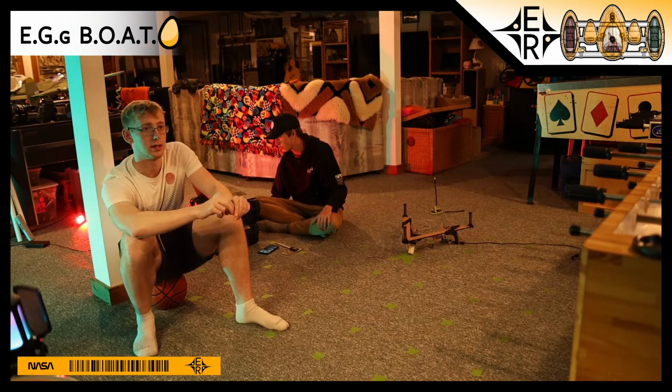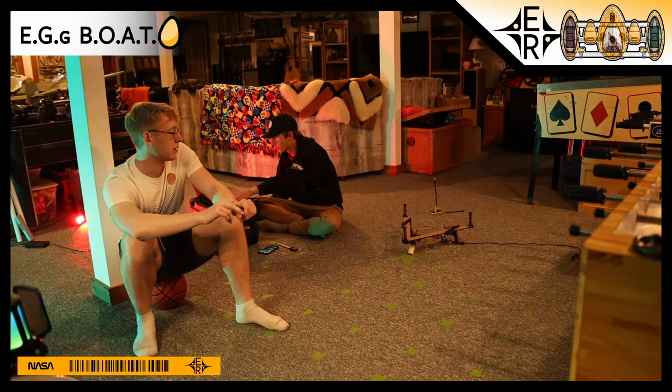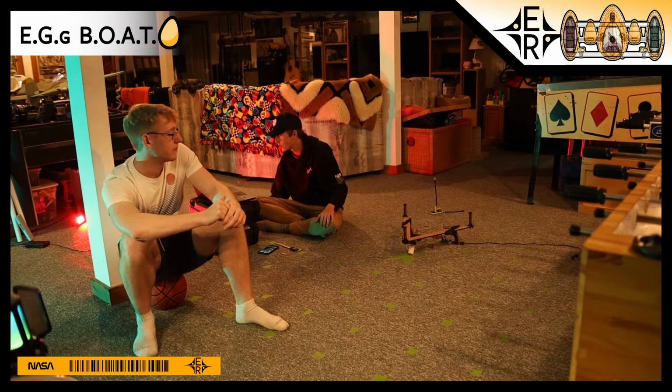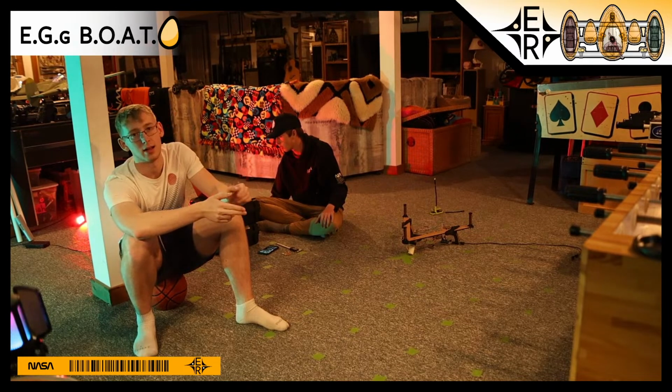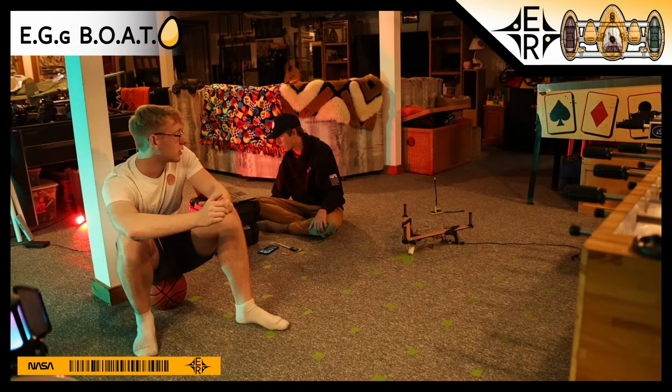The first pair gives us information about the phase difference between our reference and antenna 2, and the other pair gives us the phase difference between our reference and antenna 3. Each pair correlates to the difference in phase from one of the back antennas to our front reference antenna. So that's what the system's doing.